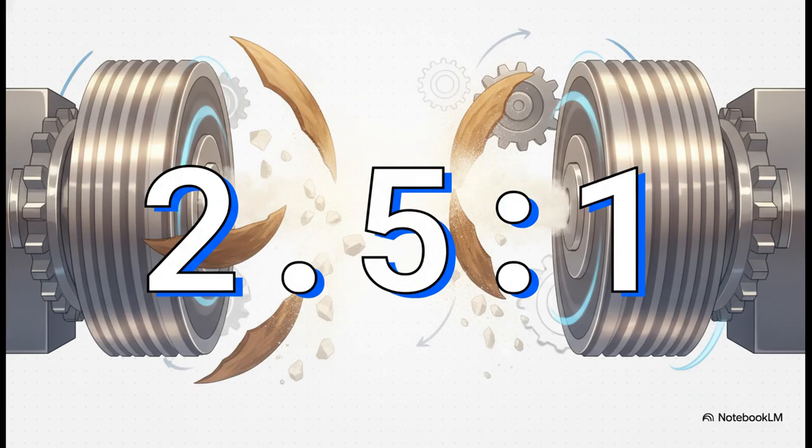These corrugated brake rollers operate in pairs, revolving in opposite directions to create specific vector forces. The fast roll travels exactly 2.5 times the speed of the slow roll. This rotational asymmetry generates the critical scraping effect.